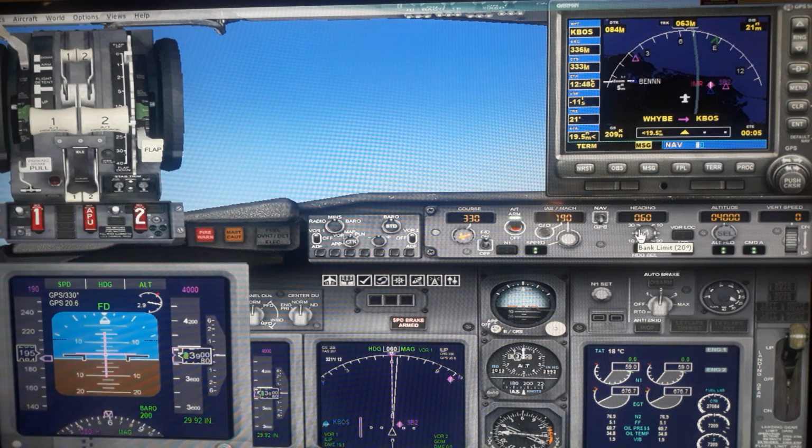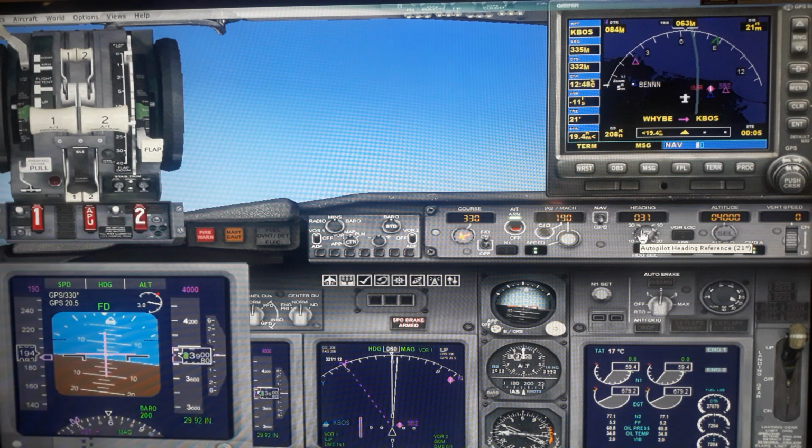Alright, now I will pause this for a minute. I will change this to heading 10. This limit got changed, this one posted. Because otherwise it will be a very large radius banking. So we put it back to 30 degree banking. You can see the bank angle is 30. Okay, now we are getting, this line is like this.